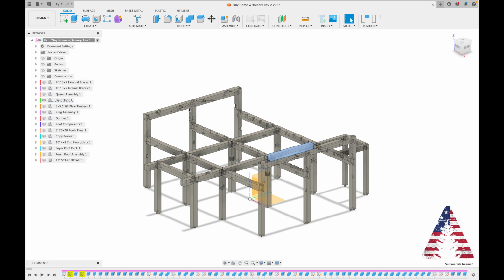And I've got these what are called principal purlins, and they're tying this structure together in this orientation, and they are mortised and tenoned and scarfed for length. These are effectively making a longer timber than I could find naturally.